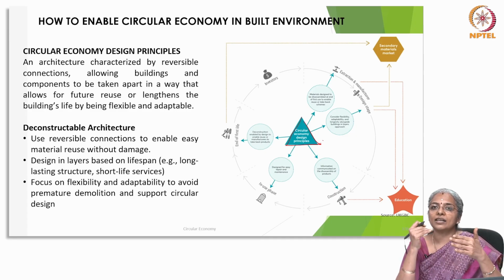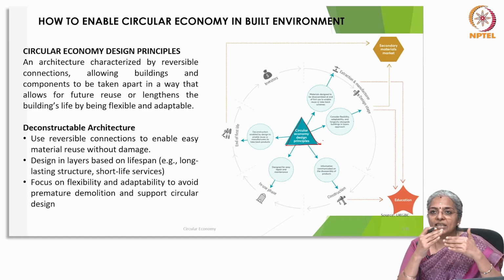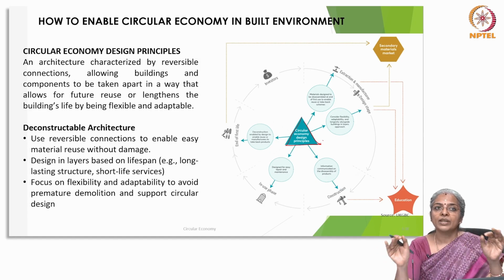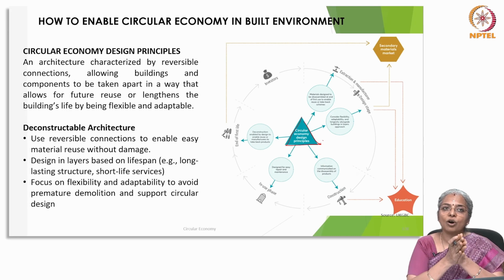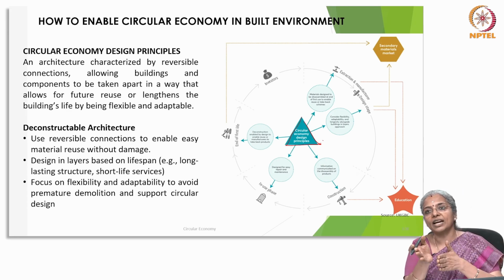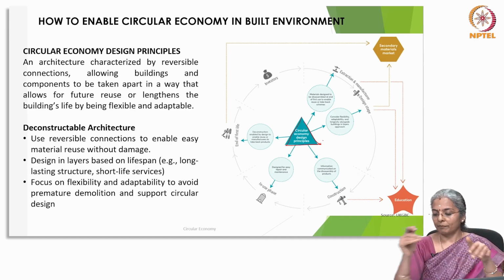So, deconstructible architecture is the way to be, where we use reversible connections to enable easy material reuse without any damage. You design in layers based on lifespan. For example, you can have a long-lasting structure with short-life services. We should focus more on flexibility and adaptability to avoid premature demolition and support circular design.